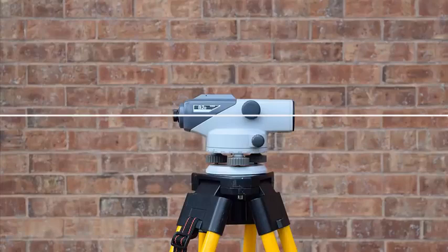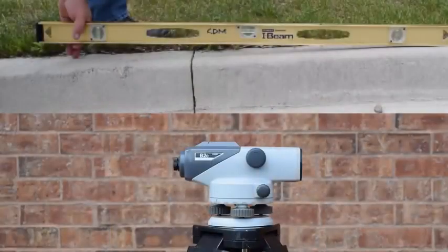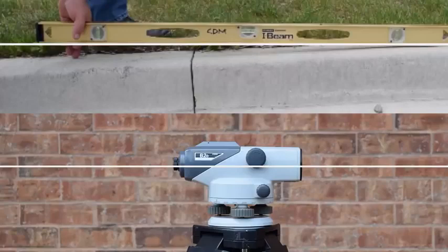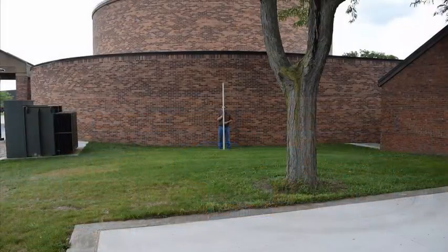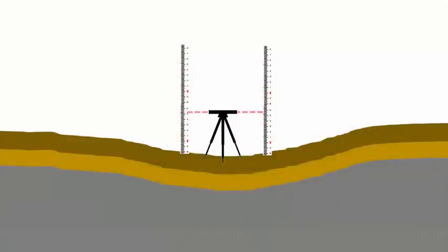Well, how does that work? The level telescope contains a crosshair. The horizontal crosshair defines a level plane in all directions. That is, your line of sight through the horizontal crosshair is a level line, perpendicular to gravity. Just like the underside of the carpenter level was held level just a few moments ago, now your line of sight is level. Because the optical level is telescopic, you can see farther. If you can see farther, then the distance between your measured locations can grow.